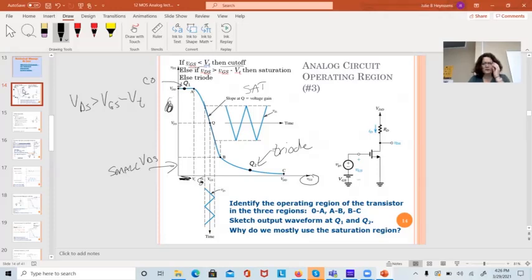And so what I want to do here is I put a DC signal on the gate that puts me at this Q point. So this is my big V, big G, big S right here. I put an AC signal in series with it, so they're going to add. And I put those both on the gate. There's my AC signal, my little v, little g, little s. I put that in on the gate, and my output I want to take off the drain. So this is V in, this is V out.